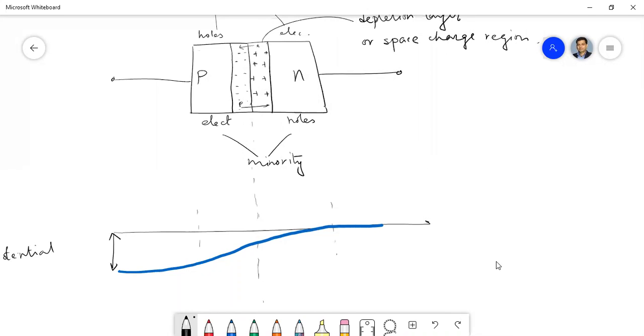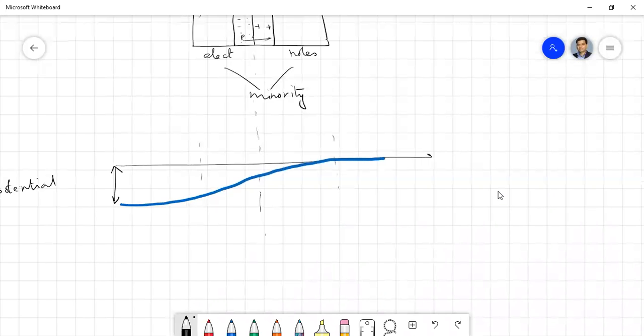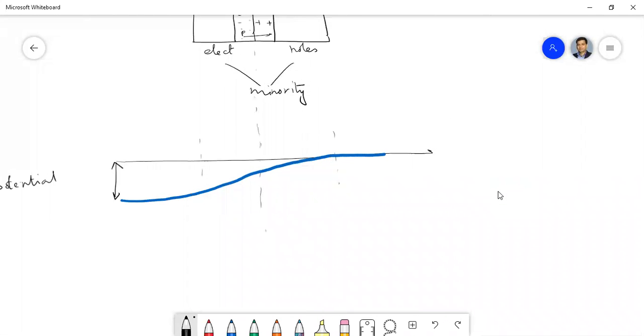Okay, so that means the forward bias is not only when we are connecting the p side to the positive and n side to the negative. The forward bias means the change in carrier concentration along the depletion layer. Okay, so you should remember that forward bias and reverse bias are a complete device phenomena, not external phenomena. Okay, so let me discuss when the forward bias occurs.